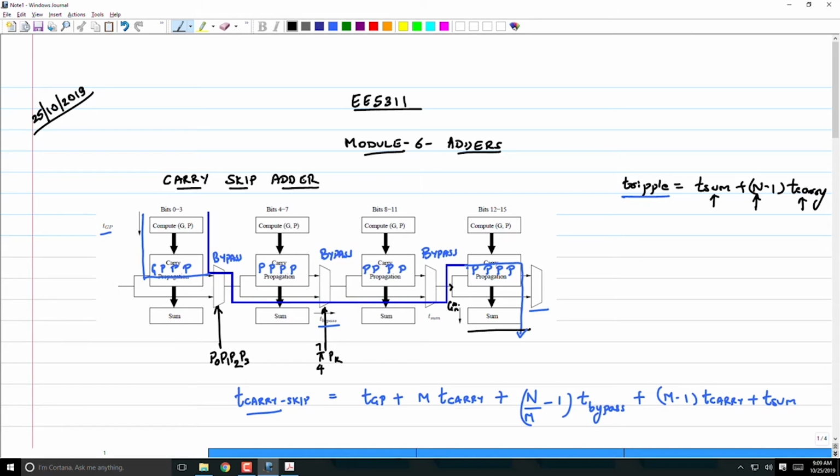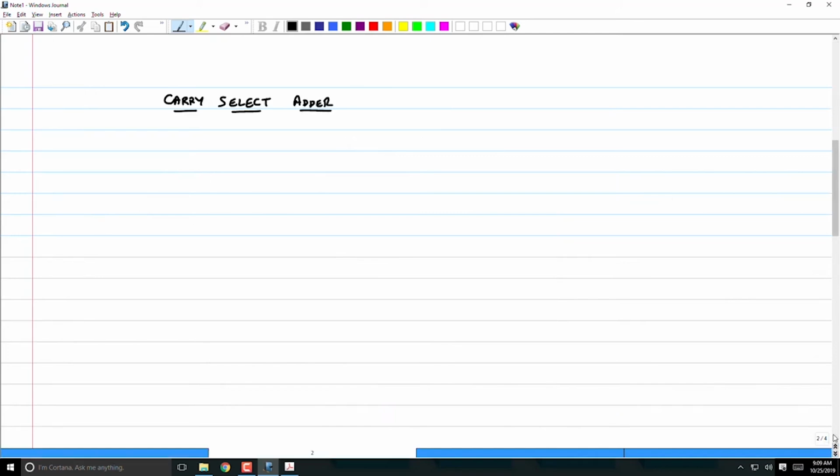The aim here is to improve performance. My power can go up, my area can go up. There is no problem. If area goes up, power will go up, because width goes up and therefore capacitance goes up, and dynamic power C VDD square will go up. But it's okay. Ultimately, I want performance.